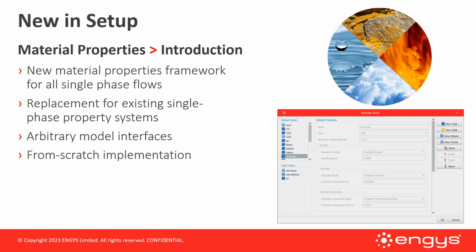The new material properties library offers a simplified interface, as it consolidates all material properties into a single file. This is a significant improvement compared to the previous library inherited from OpenFOAM, which used different interfaces depending on the selected solver. For instance, incompressible solvers required a transport properties file, while multi-phase compressible solvers used a thermophysical properties file. Additionally, other properties such as Lagrangian particles and radiation had their own separate interfaces.